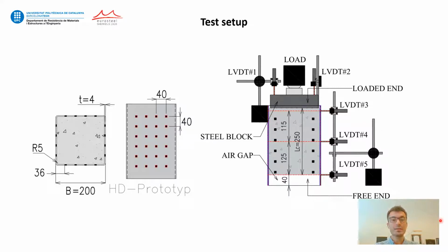In the push-out test setup, the force is only applied to the concrete core to push it out from the tube. Given that, along the 50 mm length at the loaded end, the steel tube is kept flat, and it has no punch. This is to avoid the contact of the load spreader block with the punch crowns.